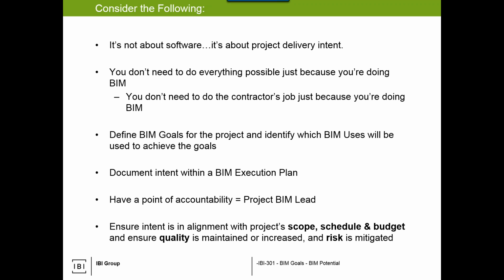Define goals for the project. So you may say, I need to do drawings, and in order to do my drawings, I need to have a model, and I need to make sure I'm hitting LOD 300 so I have meaningful drawings. And you know what? Let's visualize, so let's engage the advanced Viz team, and we'll have design review sessions every month.